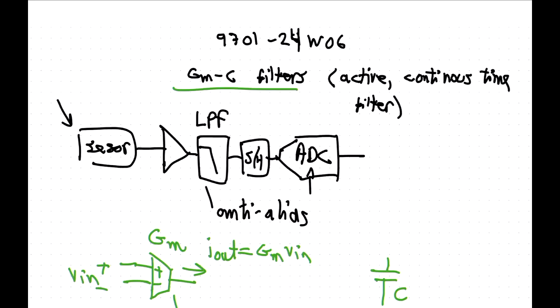Yeah? So if you sample at 1 megahertz, you might want to choose that frequency to sit well below the Nyquist rate, so maybe sitting it at, I don't know, 200 kilohertz or something like that, depending on how greedy you are. And if you say 200 kilohertz, still quite greedy, so you need to have more than a first order filter. You probably want a second order or fourth order filter, so you have a nice steep roll down. So if you choose, let's say, a third order filter, you get 60 dB per decade. Then you can work out where you should put your poles in the filter.